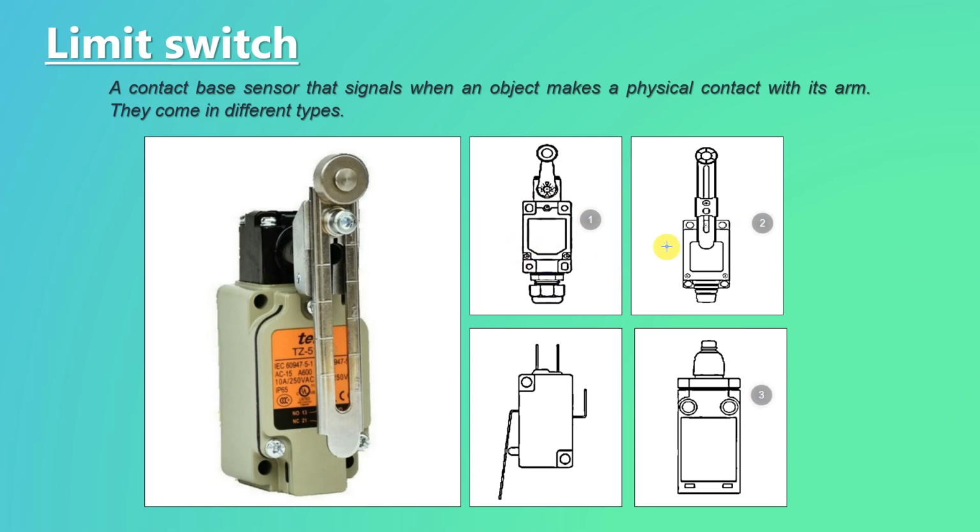Another difference that you can find immediately is that in these three limit switches, 1, 2, and 3, the contacts are internal. To expose those contacts, we have to remove this set of screws, remove the cover, make the connection, and put it back again in order to secure those connections. In the case of micro switches, because there is not enough space internally, the connections are external, so that wire can be soldered externally directly onto the terminal.